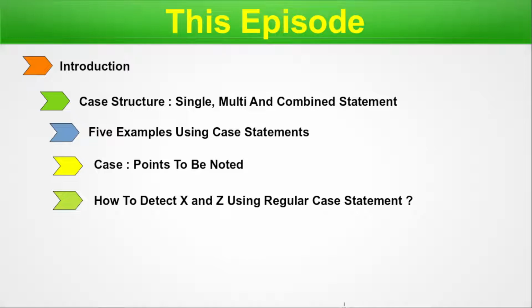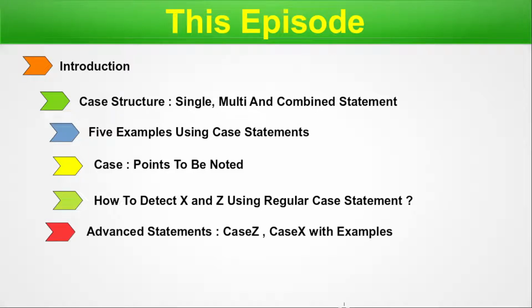And remember, this is a very good question for any interview in Verilog because we also have case X and case Z in Verilog. However, we can use a general case statement to detect X and Z. So in this point, we are going to talk about that only. Next, we will talk about the case Z and case X examples. Next, we will talk about the casex and casez with examples.